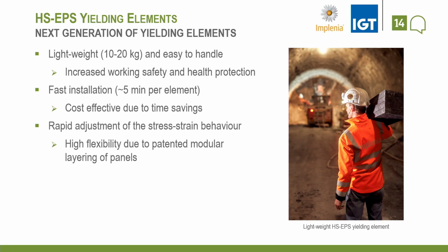For the designer, the flexible stress-strain response is essential, because he can be extremely flexible if ground conditions, for example, change, or also from his design perspective, he can say which stress-strain response he needs to get a good utilization of the lining, and we can design this tailored. The flexible sizing is another important thing. If you have, for example, 1 meter round length, geological conditions get worse, you have to reduce the round length, you can simply cut the yielding elements with a saw directly on site, and you don't have to stop and order a different configuration.